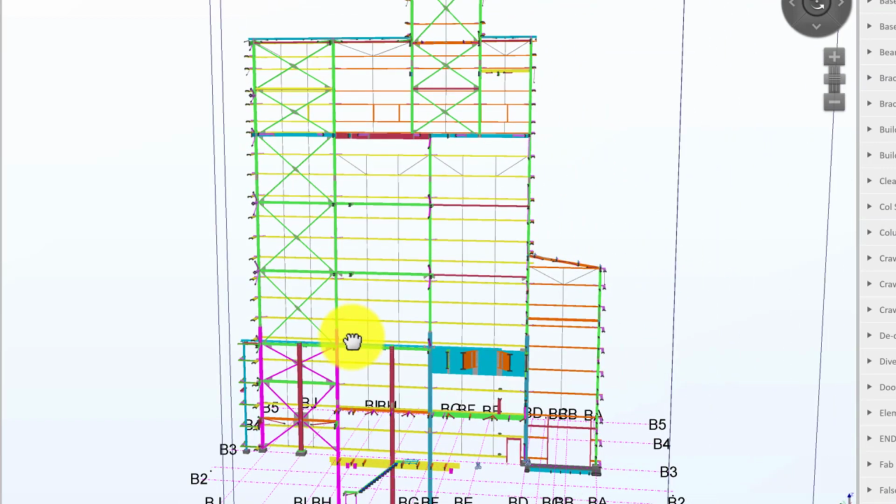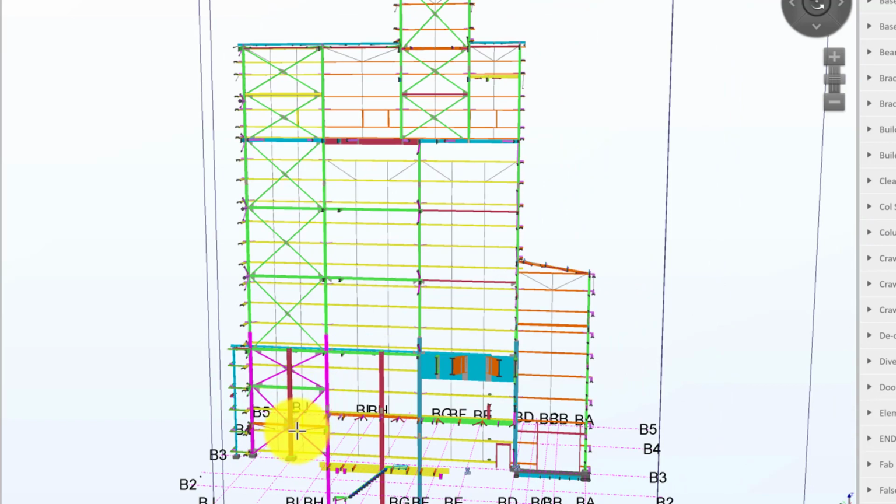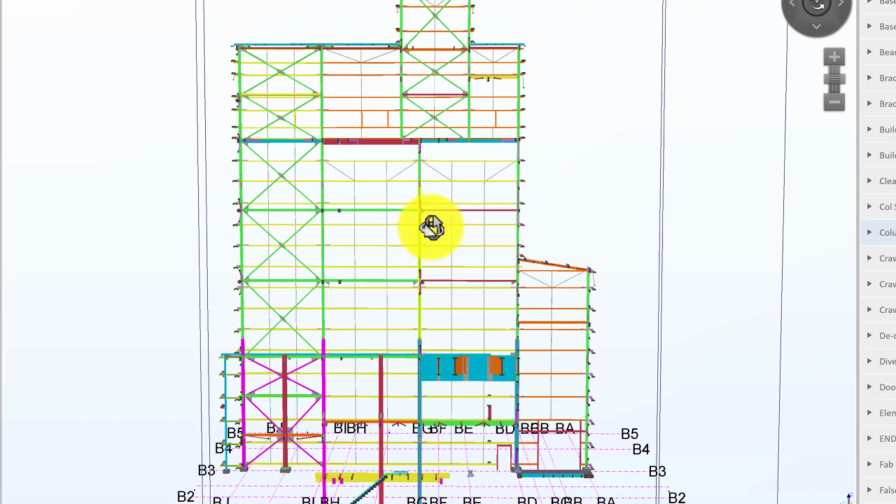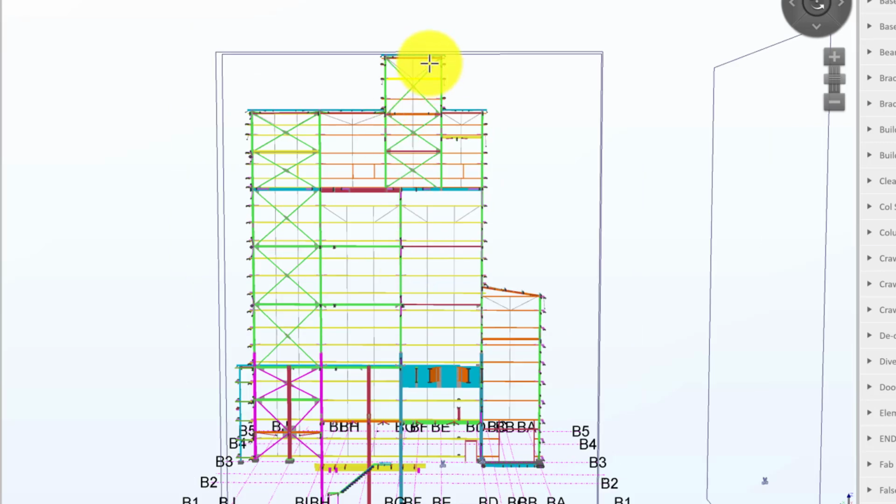The geometry is not perfectly regular because of where the floors were, but very heavy bracing all the way up this left hand side, and within a piece that came out of the top of the structure where the bucket elevators sat, and then there was some more cross bracing, so that load would come down, come to the floor, and then be carried across horizontally through the floor to this section, and then loads would be carried all the way down to the foundations.